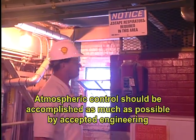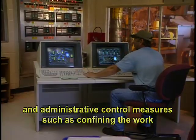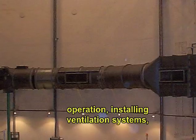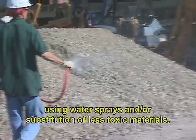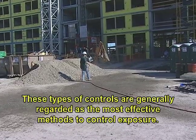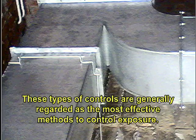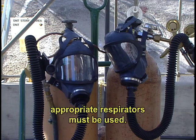Atmospheric control should be accomplished as much as possible by accepted engineering and administrative control measures, such as confining the work operation, installing ventilation systems, using water sprays and/or substitution of less toxic materials. These types of controls are generally regarded as the most effective methods to control exposure. When effective control measures are not feasible, or while they are being instituted, appropriate respirators must be used.